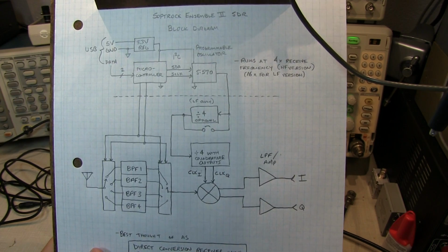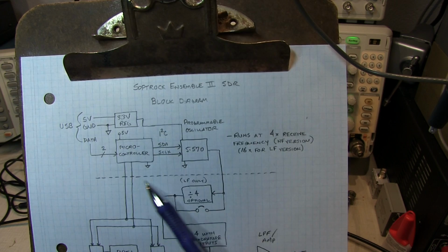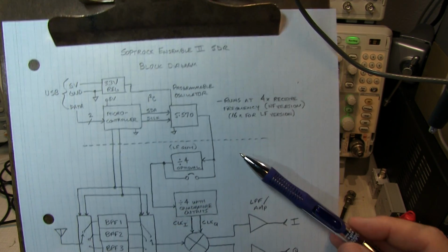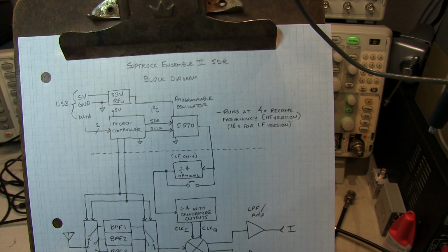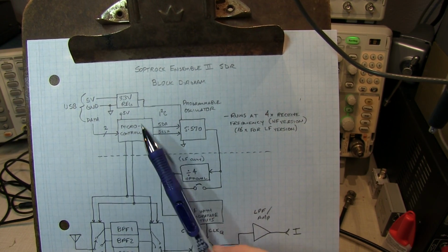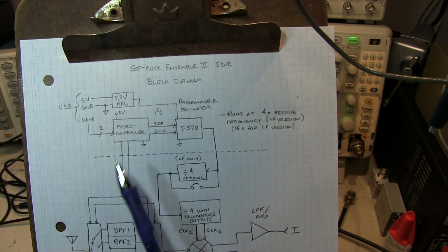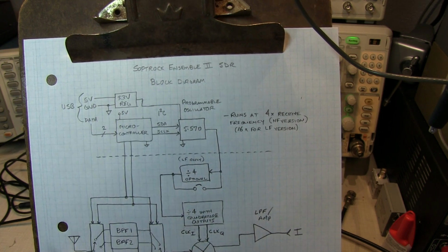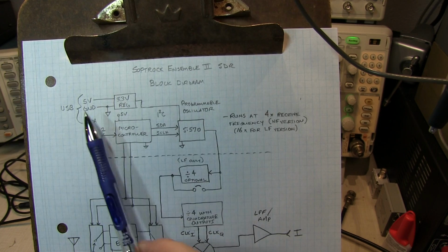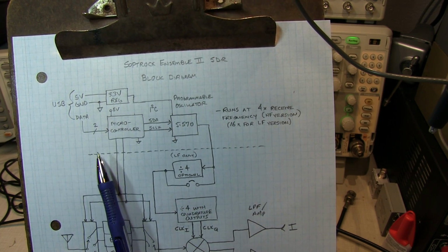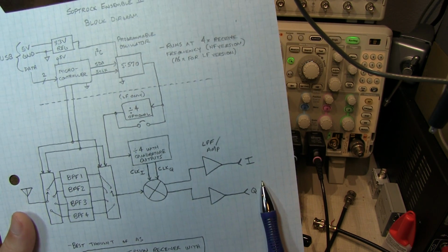One more thing I want to mention here on the block diagram is this dashed line. That dashed line indicates that there are two different power supply domains being used here. All of the digital interface for the USB to control the microcontroller and to generate the clock is all powered off of the USB port from the laptop. That provides sufficient power, but also might be a little bit noisy. Plus you also run the risk of ground loops between the USB ground and the sound card inputs here.